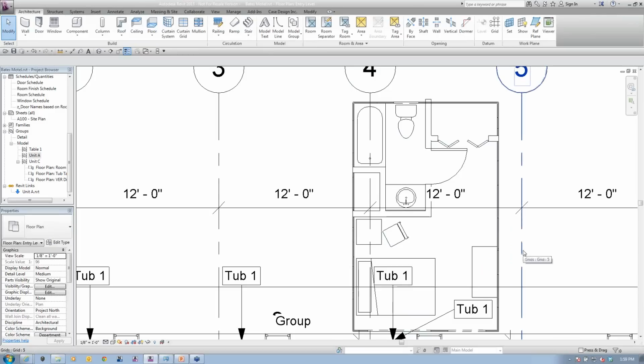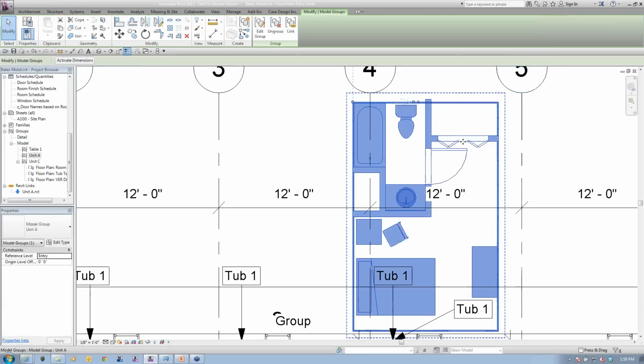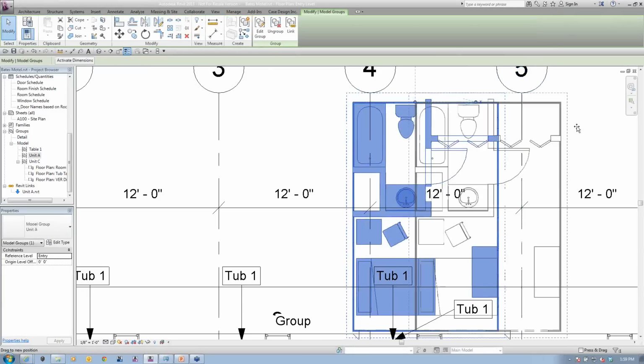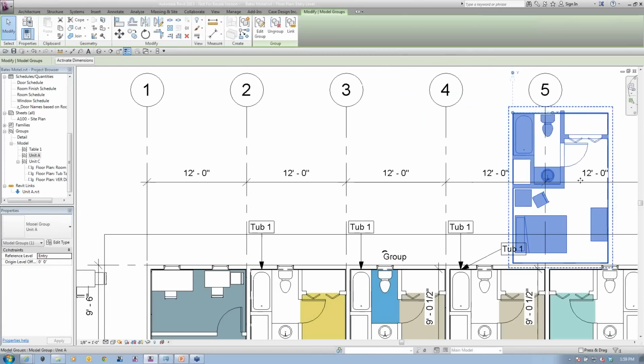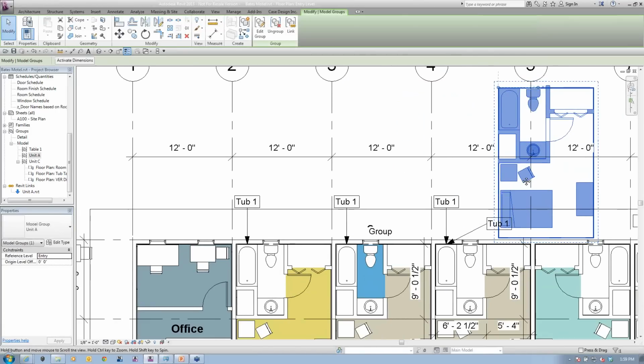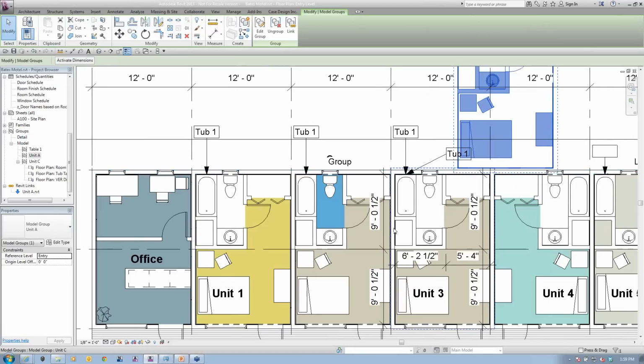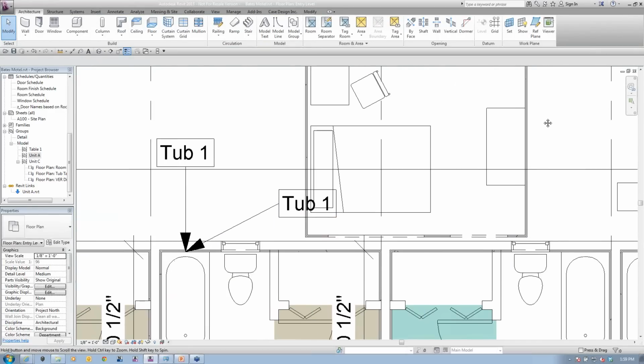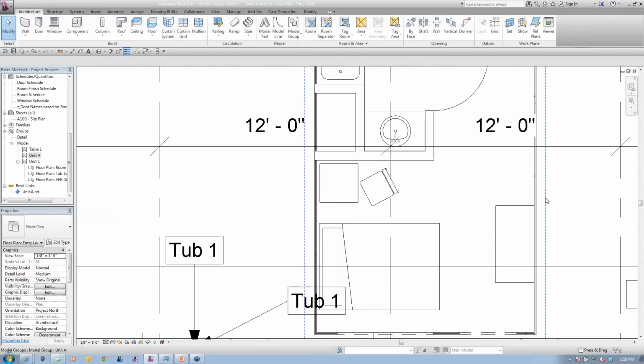is this. When I start to do links and export this out as a link file, I want to be able to have the rooms form properly, but I don't want to disturb the other things that are going on for the rest of the house. If I need to have firewalls within my rooms or room separators, I'm going to keep those native. So all the structural elements will be in the main file, or in a separate link or something like that. But for the unit plan itself, what we've done is make a wall that's, in this case, 2 layers of gyp, and put that in there.